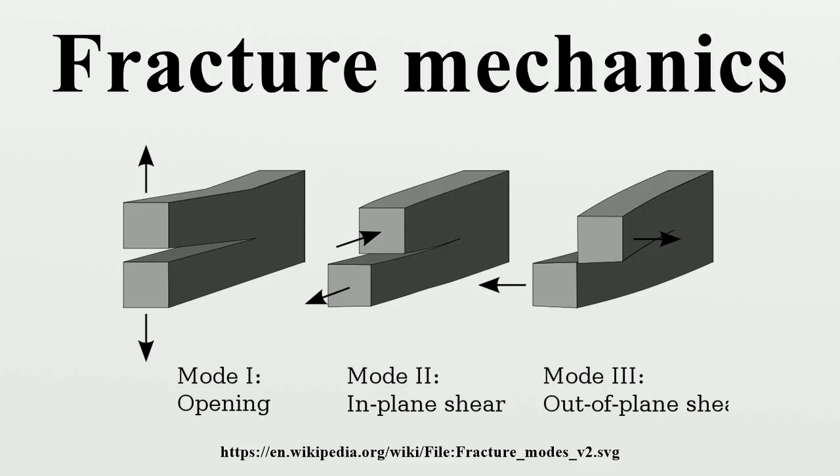There are a number of alternative definitions of CTOD. The two most common definitions are CTOD as the displacement at the original crack tip and the 90-degree intercept. The latter definition was suggested by Rice and is commonly used to infer CTOD in finite element measurements. Note that these two definitions are equivalent if the crack blunts in a semicircle.